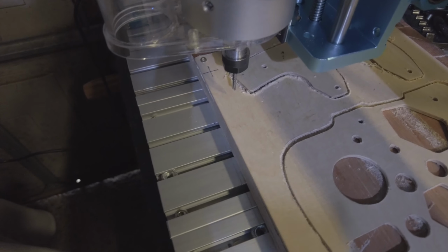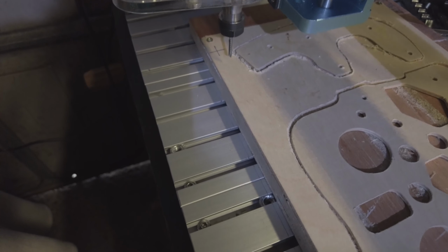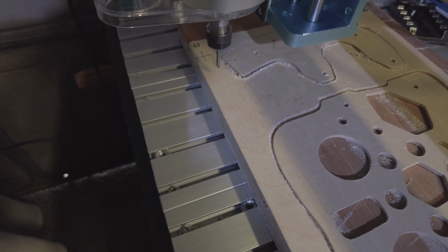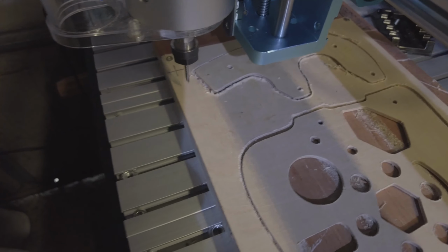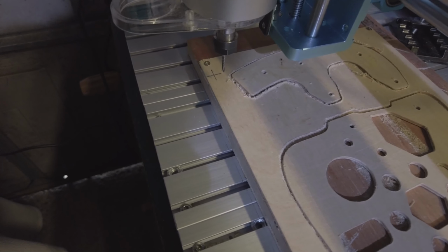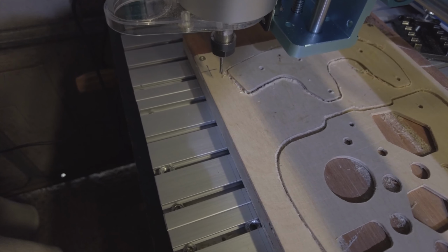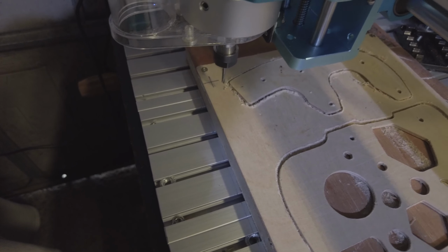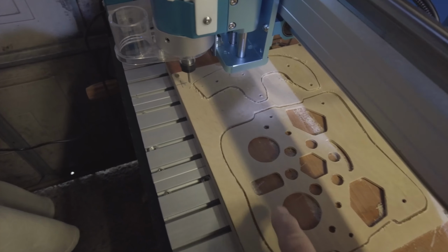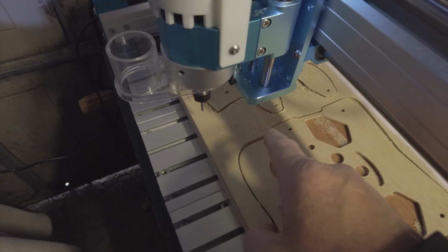In my other videos, what I was trying to show is that by using the coordinates on the offline control, you can pick up if anything does go wrong. I've never had a problem when I'm running toolpaths, however many toolpaths and cutter changes, it will always go back to that work origin. If I moved it right across to somewhere here, it will go back to work origin before it starts.